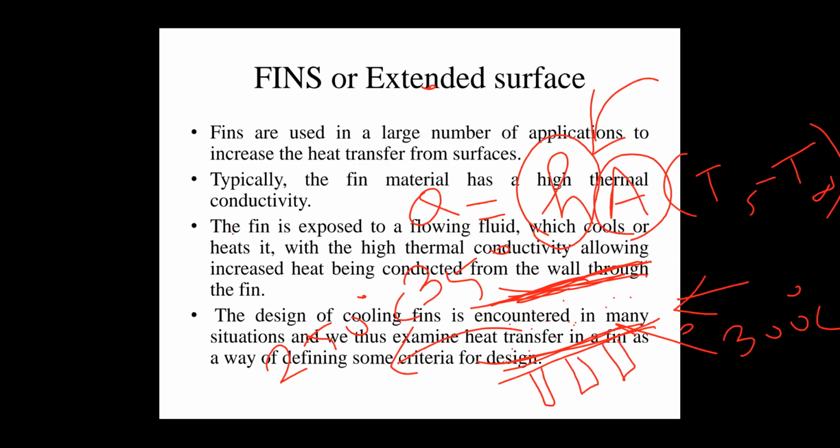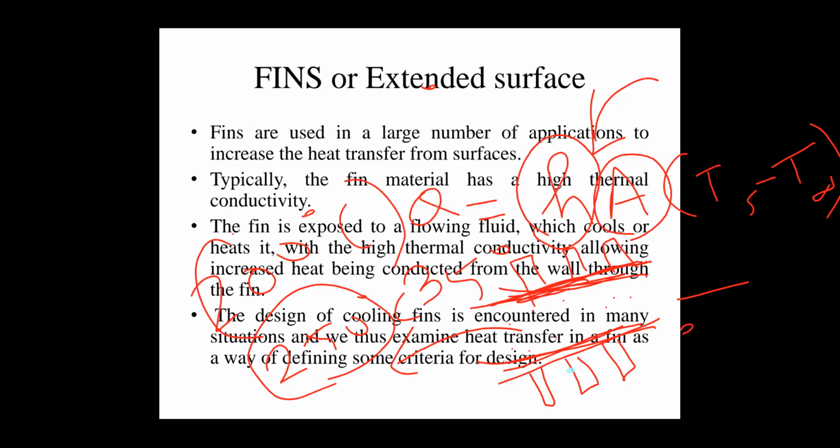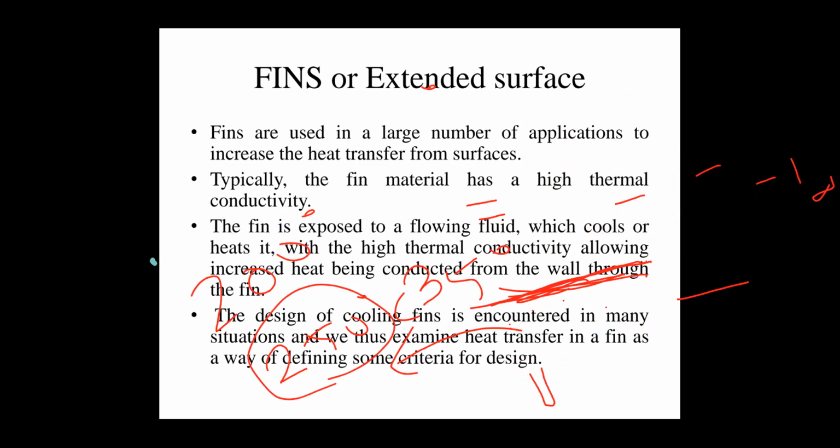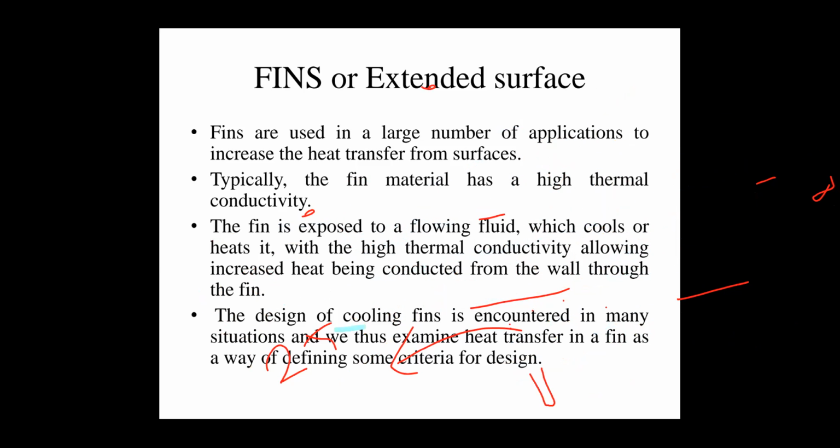So this is the surface area. By increasing the surface area, the heat transfer or heat dissipation rapidly increases. With a 250 degrees Celsius outlet, using the fins we get 200 degrees Celsius. It consumes less time. So this is the extended surface. The extended surface, otherwise called fins, increases the heat transfer rate by increasing the surface of heat transfer. A surface used to increase the heat transfer rate is called an extended surface.